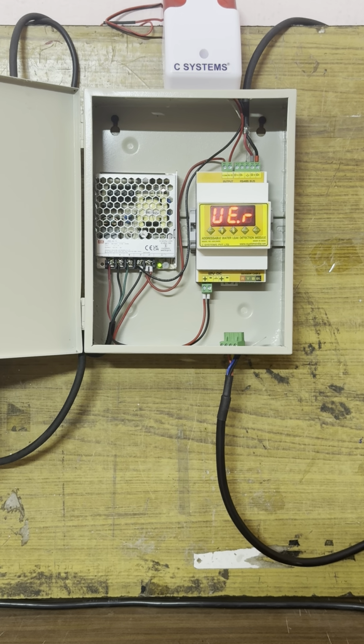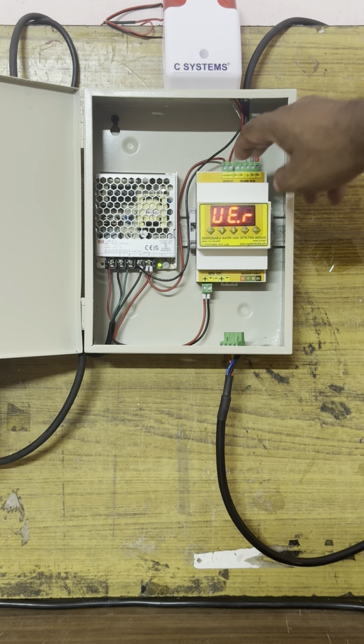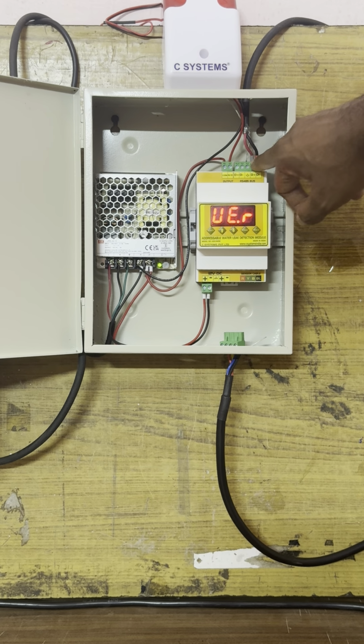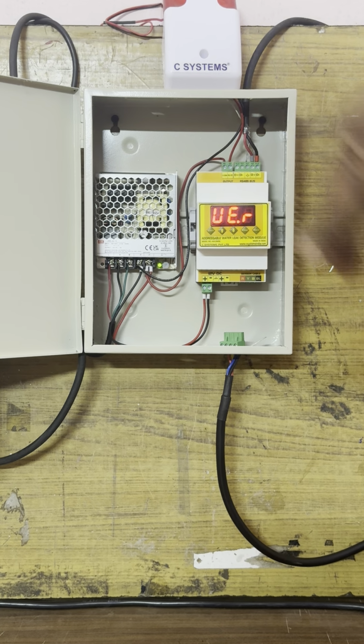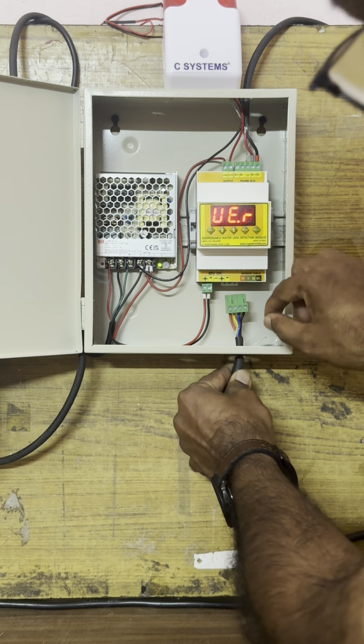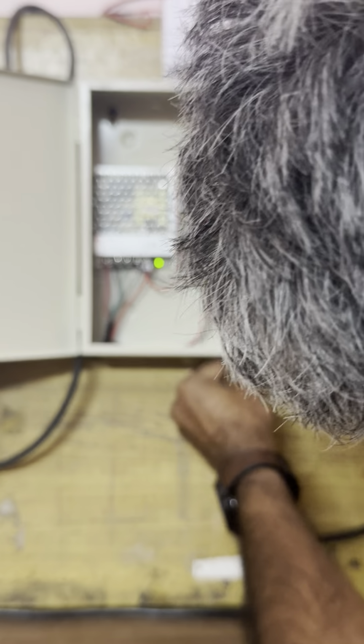So before entering the parameters, make sure the sensor cable is connected and the communication cable is connected to the master panel. Before connecting these two, do not attempt to configure the module. As you see, we have connected the communication cable between the master and the module, and I am going to connect the sensor cable. Sensor cable comes with a pre-defined, pre-insulated, pre-fabricated 4-pin connector.